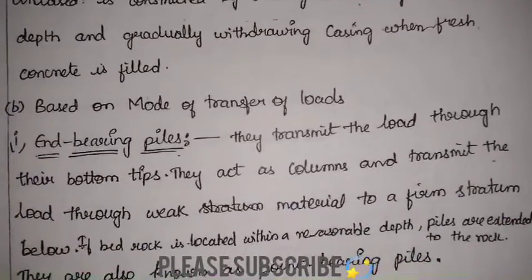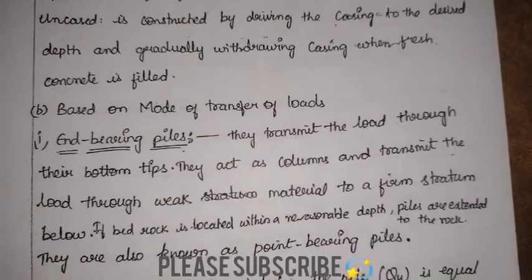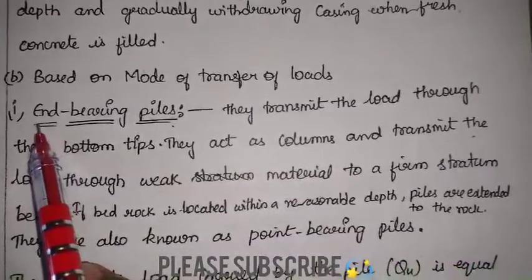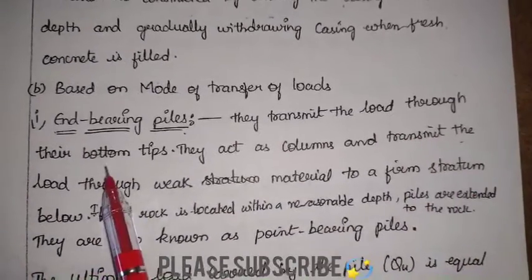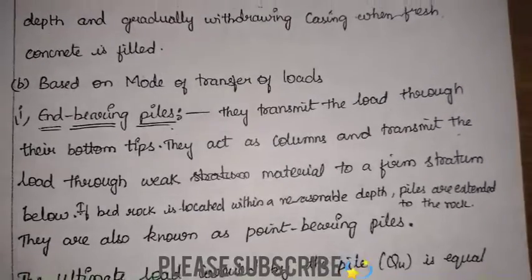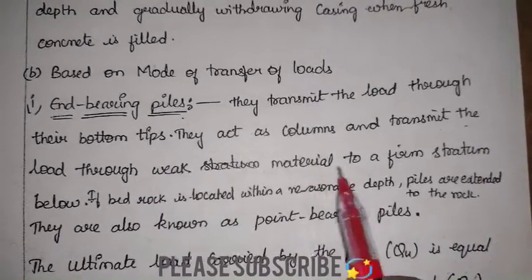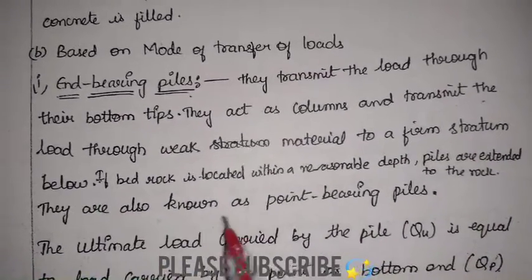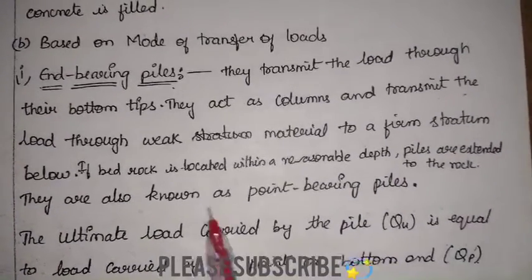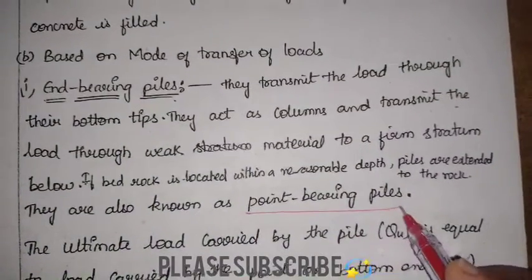Next, based on the mode of transfer of loads. That is, on which part the load is transferred. So end bearing piles. Here the name itself suggests that it is end bearing. That is, they transmit the load through their bottom tips. Whatever the end part, the tip part is there, we are transferring the load with that. So they act as columns and transmit the load through weak material to a firm stratum below. If bedrock is located at a reasonable depth, piles are extended to the rock. So they are known as point bearing piles. End bearing piles are also known as point bearing piles.